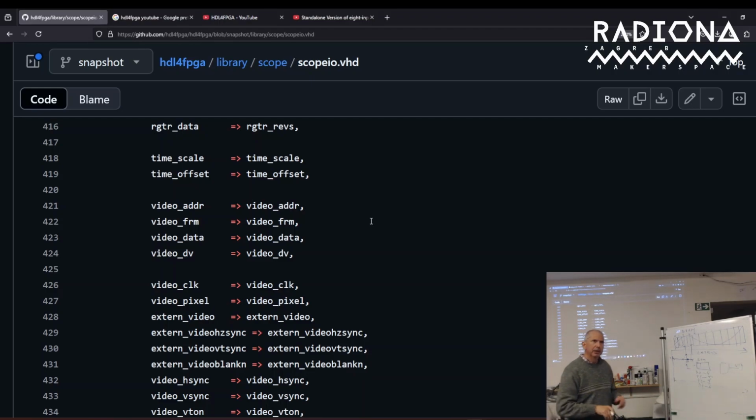So actually it's one tap of the pipeline coming out. Yes, it's align. I didn't look at this code, but you are having variable latency delays for various stages of the signals. For some signals, you have to delay really long, but some are already delayed through some arithmetics or whatever, and then you have to delay them a little bit less. And some are so slow that you don't have to delay them at all. But they all have to come out in the video order at the right time, synchronously, without any clock. Exactly. Crazy.